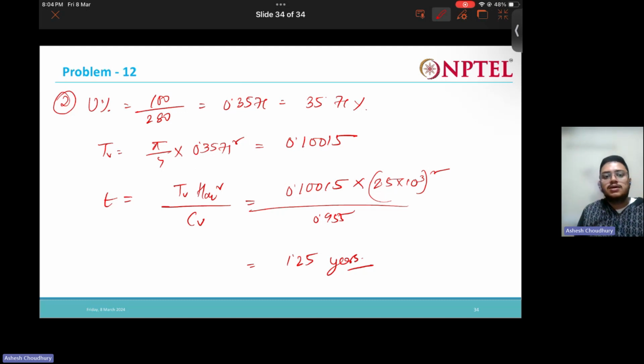We want to accelerate the consolidation process even before the construction, so that the consolidation happens faster, and in the later stage, after a structure is built over that soil, the structure does not undergo unnecessary settlements that might cause damage to it. So this is why this consolidation calculation is very important to us.